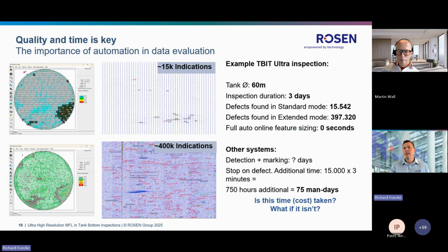It's not only important to define the proper repair method, because of course internal indications are repaired differently than others, so operators want to know if the defect is on the top or on the bottom side. It also plays a crucial role for the depth sizing, because an amplitude of the same size on the top side corresponds to a different defect than on the bottom side. Therefore the discrimination is a crucial factor in the performance, on the feature depths, but also on length and width sizing.